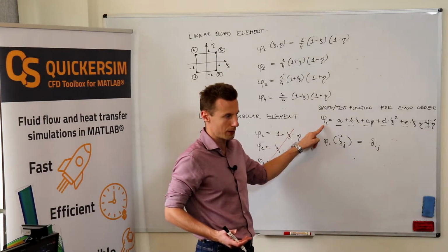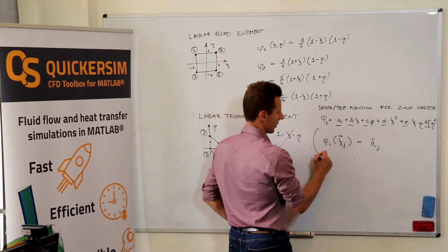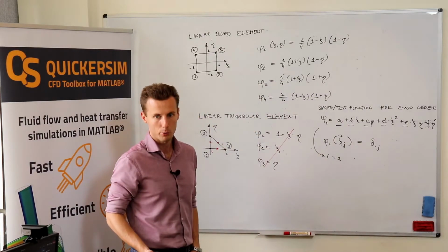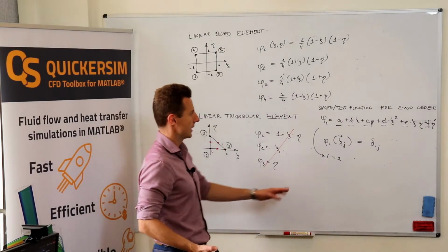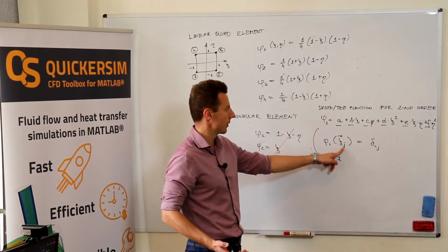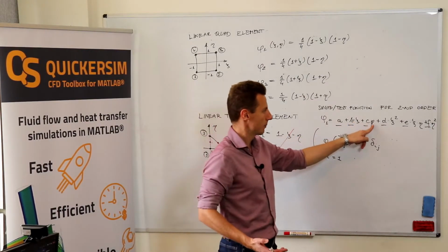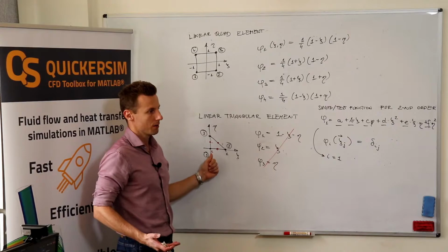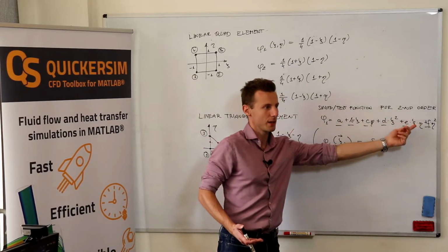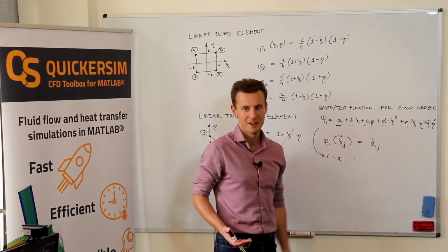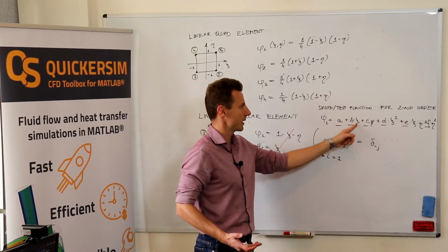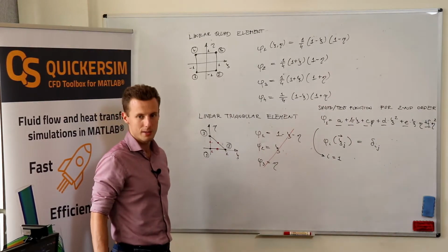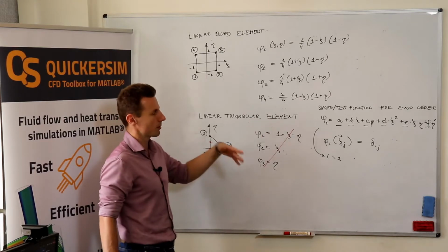Okay, how do you develop the first shape function? Well, you say, okay, i is equal to 1. And now what are my requirements? My requirements are that if j is also 1, which means that I can substitute particular coordinates of the first local node, then this formula with 6 unknown coefficients needs to give me 1. If I substitute the coordinates of that node, then it needs to give me 0. Of that node needs to give me 0, etc., etc.